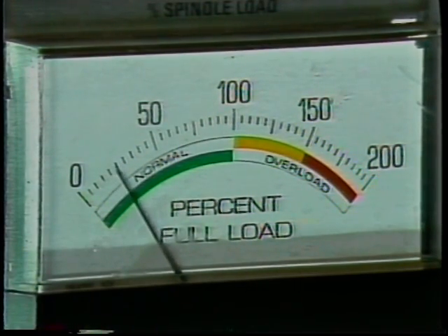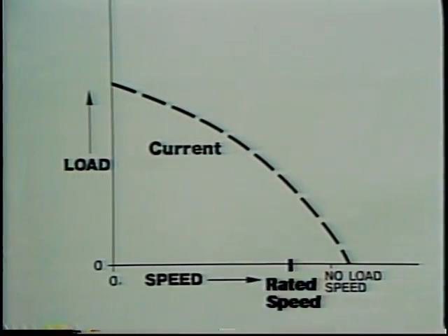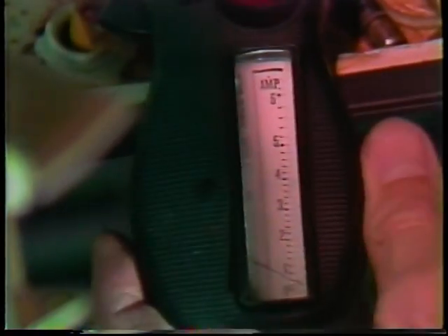That means that most motors can start and run under overload conditions. However, they will not reach rated speed, and that can be damaging, because below rated speed a motor is drawing too much current. If it is stalled or runs too slowly for too long, it will overheat, and the insulation will be damaged. The overload breakers are supposed to protect the motor by tripping, but do not rely on them completely. If you suspect that a motor is overloaded, check its speed or the current to it.